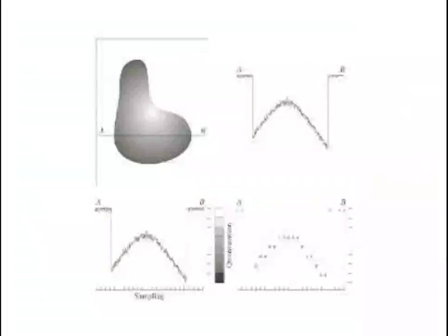The digital samples resulting from both sampling and quantization are shown in figure D. Starting at the top of the image, carrying out this procedure line by line produces a two-dimensional digital image. It is implied in the figure that in addition to the number of discrete levels used, the accuracy achieved in quantization is highly dependent on the noise content of the sampled signal.